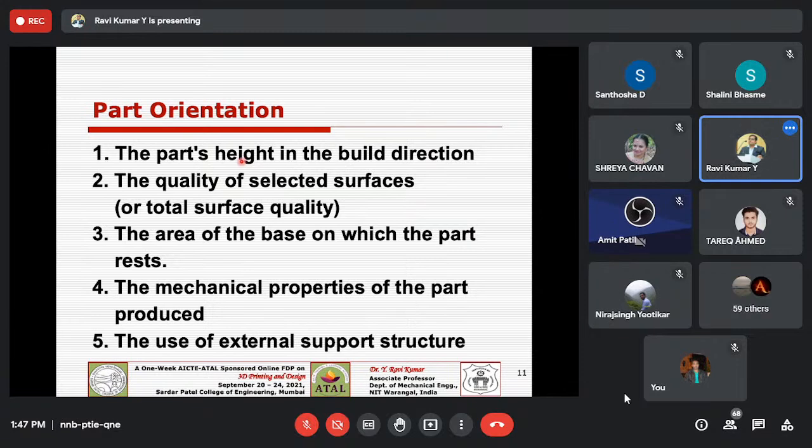As we know this technology is expensive, but how do you bridge that by adding some value to the product, by manipulating these parameters, or by exploiting these capabilities of AM, as well as the constraints or the rules that we need to adopt, right? Another criterion is the quality. Why? Because you may get better quality in one orientation than another.